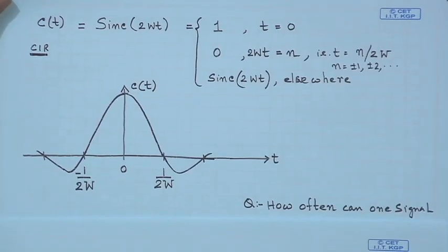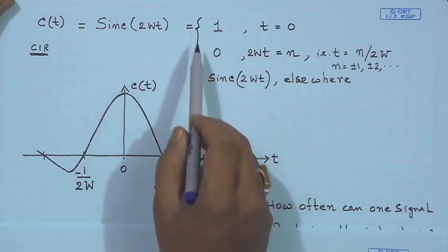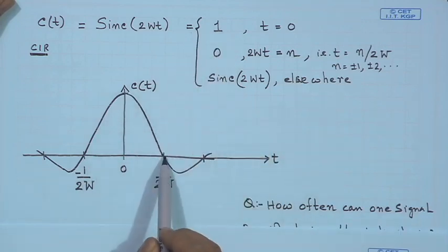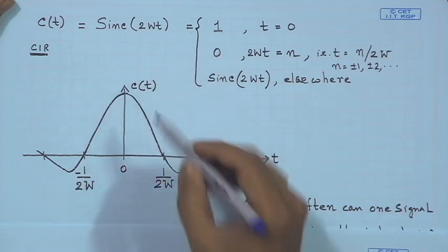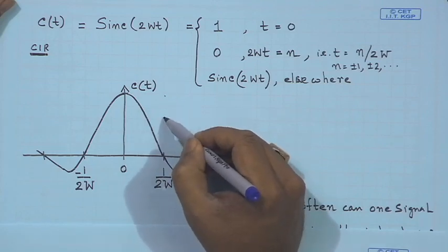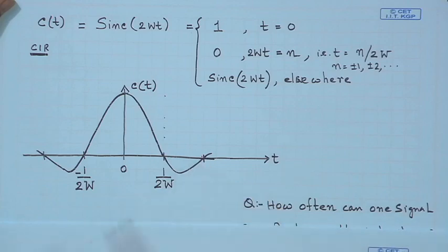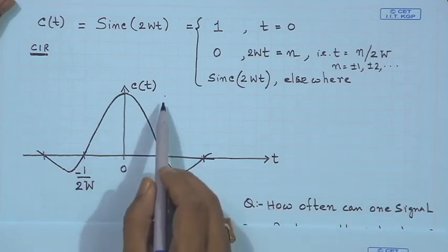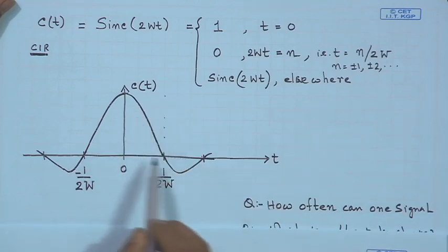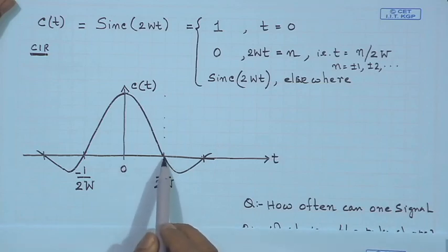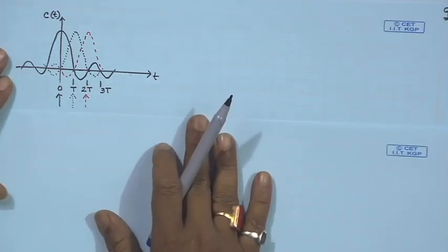Trying to answer the first question, how often can one send a signal, what we see, as described by this situation and by the figure here, is that if we launch another impulse here, we will get a 0 crossing here. That means the receiver will not encounter any intersymbol interference at the sampling instance, and that is what we depict in the figure on the next page.